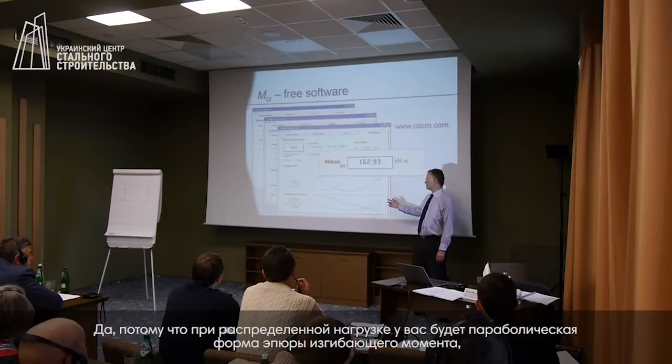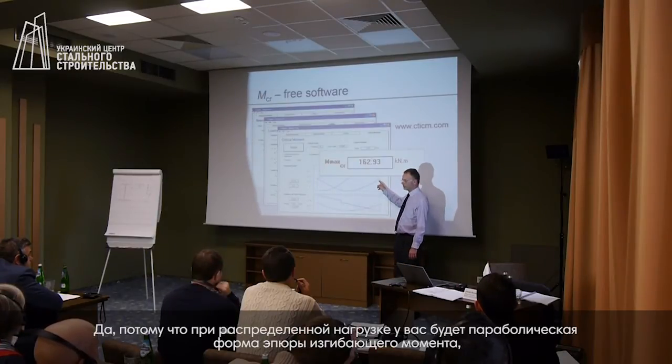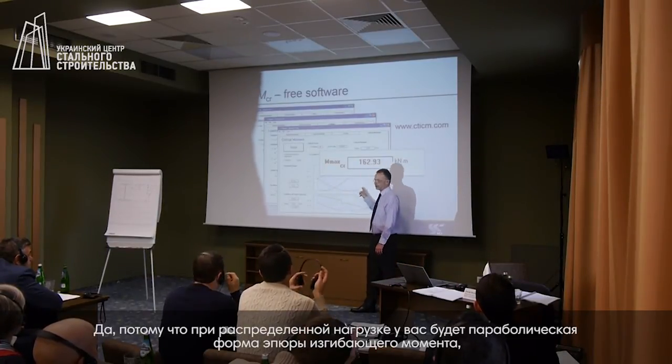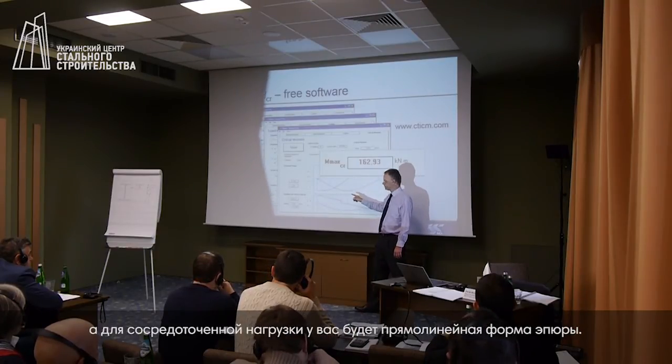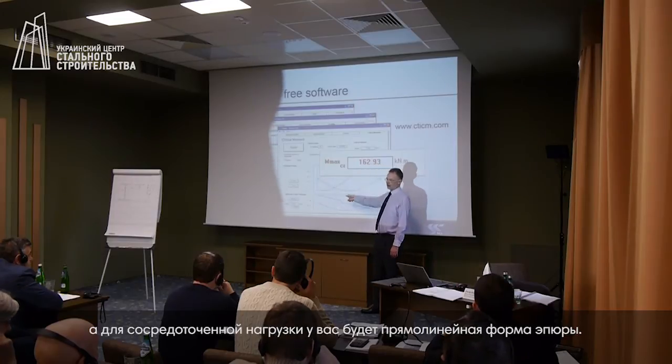Yes, because for a distributed load, you have a parabolic bending moment diagram. For a point load, you would have a straight line bending moment diagram.